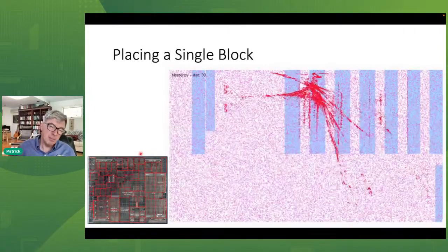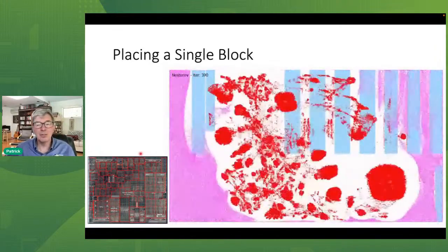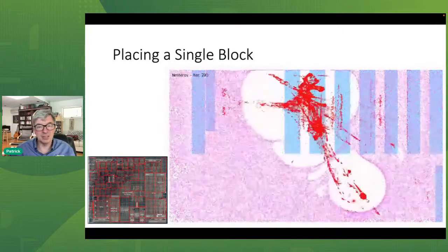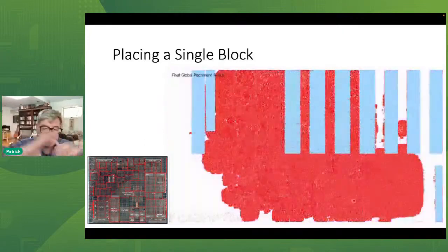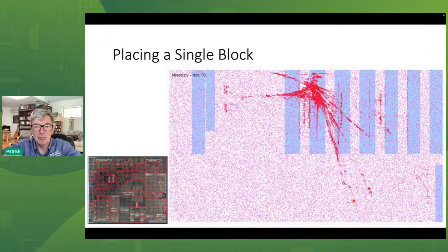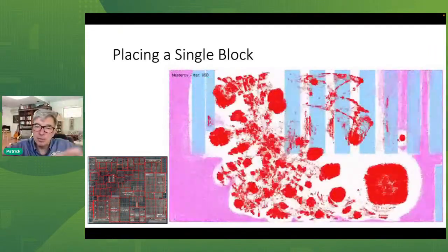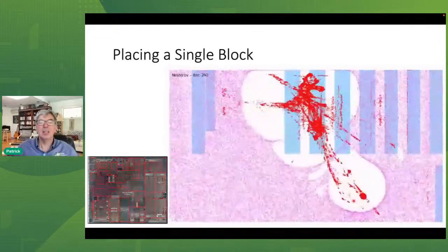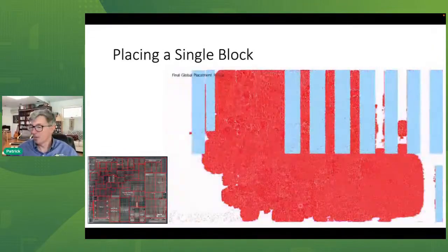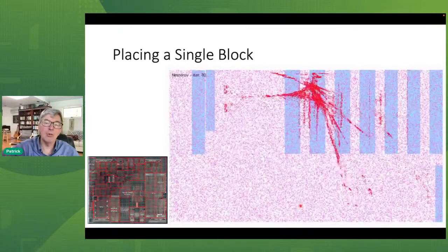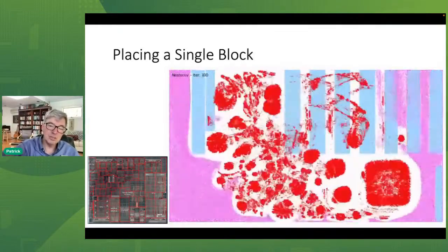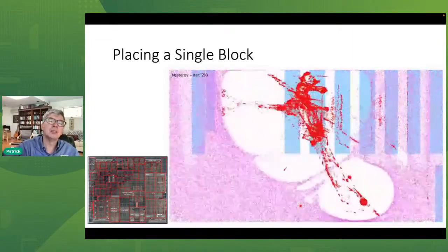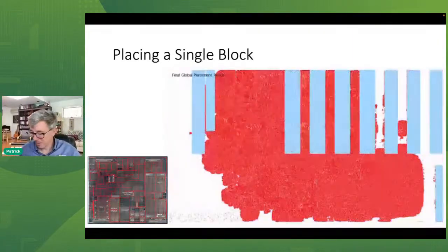There's a lot more to say about some details in here and how to make this efficient, but you can see while this expands, there are some clusters there. So some things like multipliers that want to stay together, they're still somewhat visible here, but the algorithm knows how to blend all of this together and to kind of force it optimally in the available space between that. This is a successful methodology, and it only works because all these standard cells can be treated as a point, which means that we have to assume that standard cells are roughly the same size.